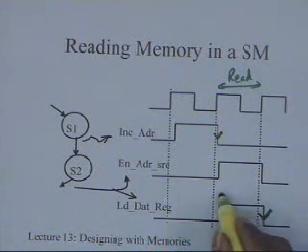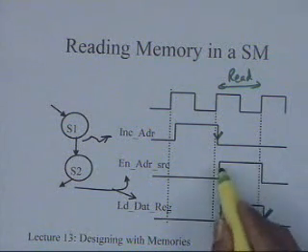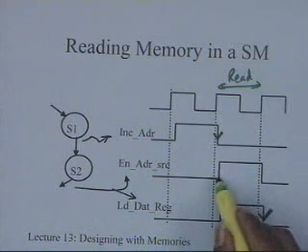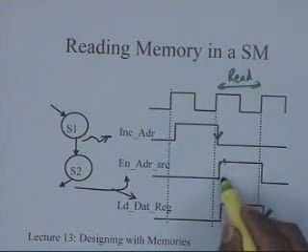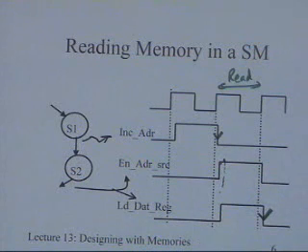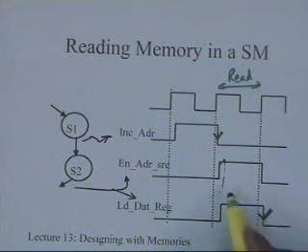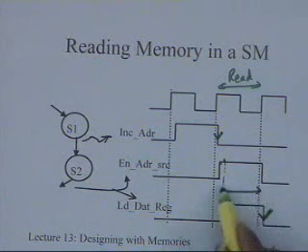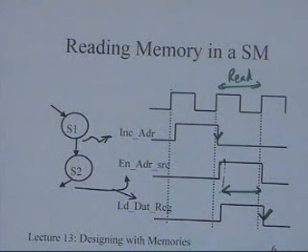So which is the time? This is the time which is used by the read cycle. I should have enough time after the address is stable. If you are doing an enable address source, the address will be stable even a little later than that, because after all, if you have a tri-state buffer, that will also have a delay to enable the address onto this. But once the address is stable, this particular time that is given should be sufficient as far as the read cycle time of the memory is concerned. And during this whole phase, the read signal can be high. I have not shown the read signal here, and that anyway has to be high because I am performing a memory read operation. So I can do that.